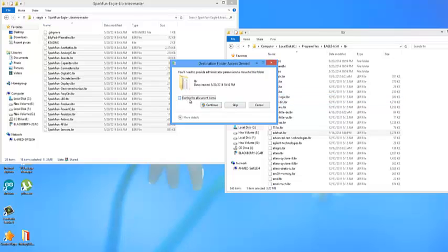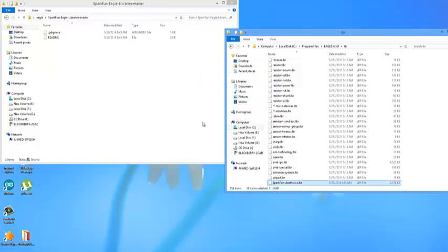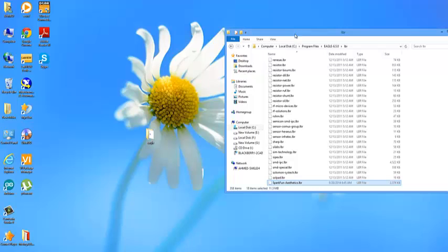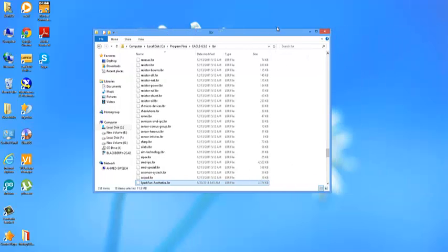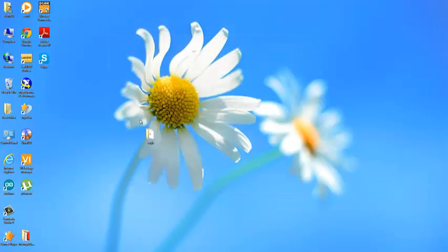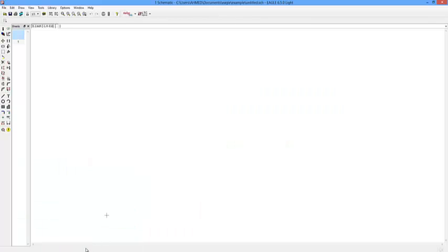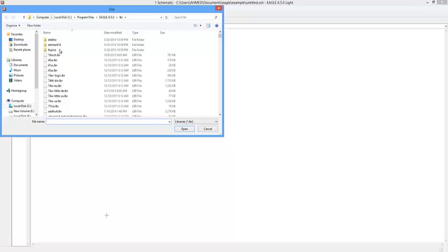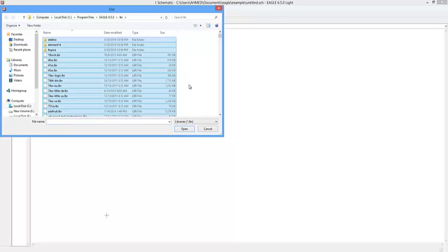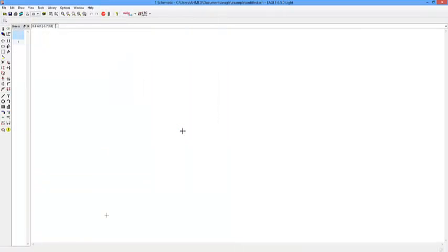Again, he is not happy. Continue. Yes. Thank you. Okay. Now these libraries have been copied into Eagle's library directory. Now Eagle will not straight away use them, so you have to tell him to use these libraries. So go to libraries and then tell him use. And when you come here, just press Ctrl A, select everything, and then say open.